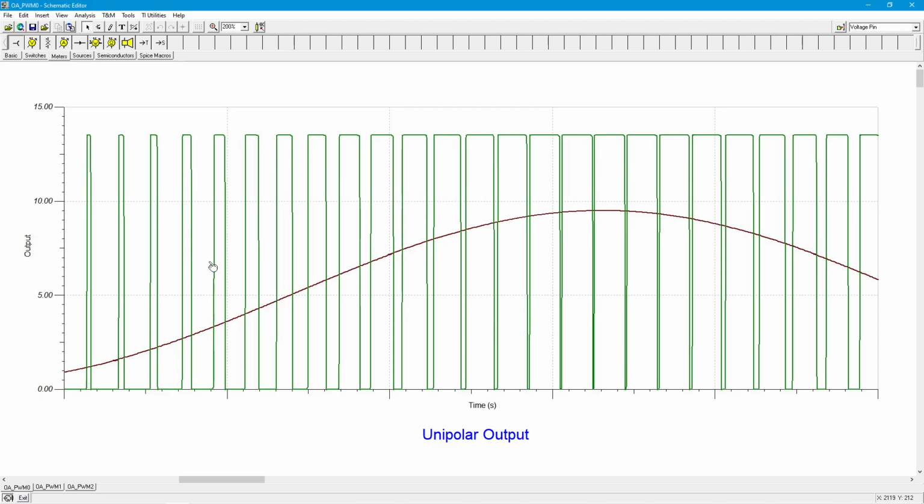So what you find is that when the signal is relatively low in amplitude, like down here, the pulses are very thin, they're very skinny. And when the signal is pretty high, we get very fat pulses, right? Obviously, the pulse can't go to more than 100%. So it can top out, and obviously it can't go below 0. There's nothing like an inside-out pulse. So in the unipolar case, this is what you would get.